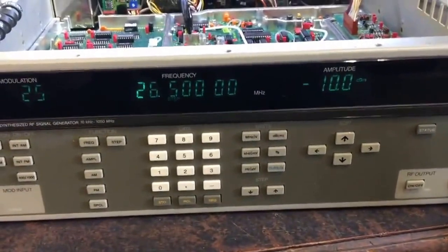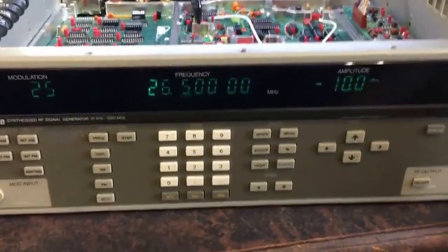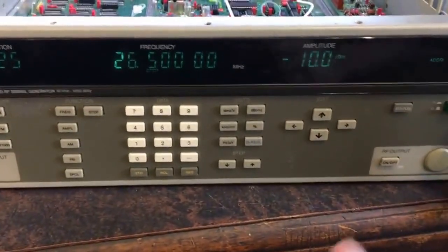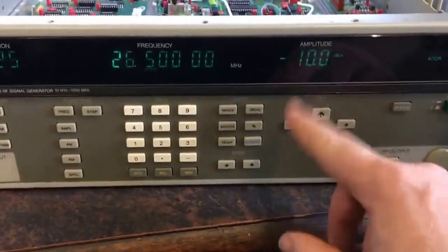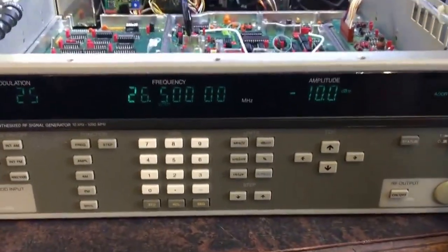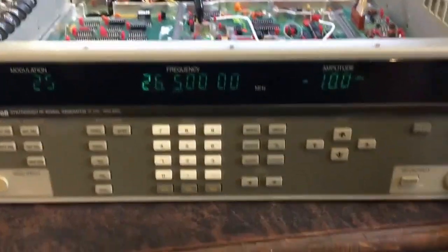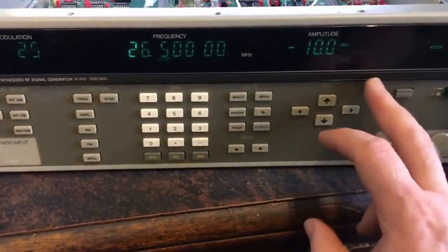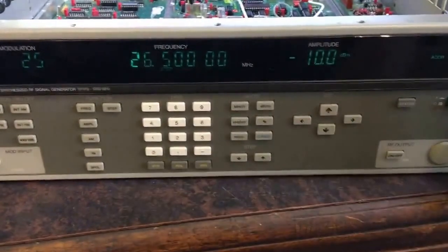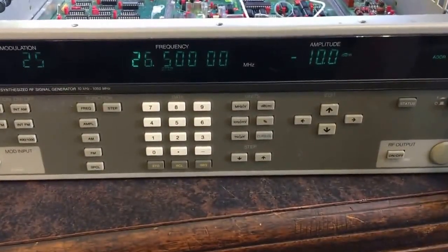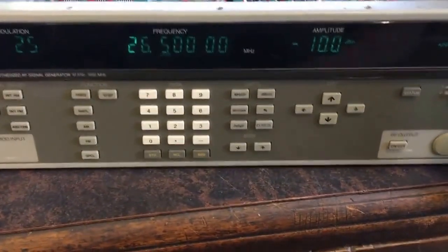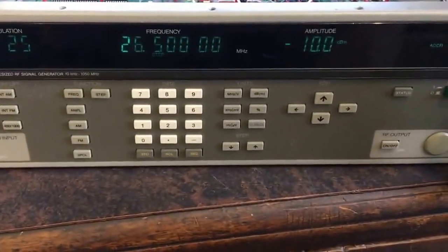So someone's obviously marked that for some reason, obviously when they're playing with it. So I'll turn it back on. All it does is compensate a little bit for the RF level drop on here. But in saying that, when I was looking at my spectrum analyzer, I've got 0 dBm output on it at the time, and I was getting around 1 dB in some cases. So it might be it doesn't actually need that compensation turned on in this case.